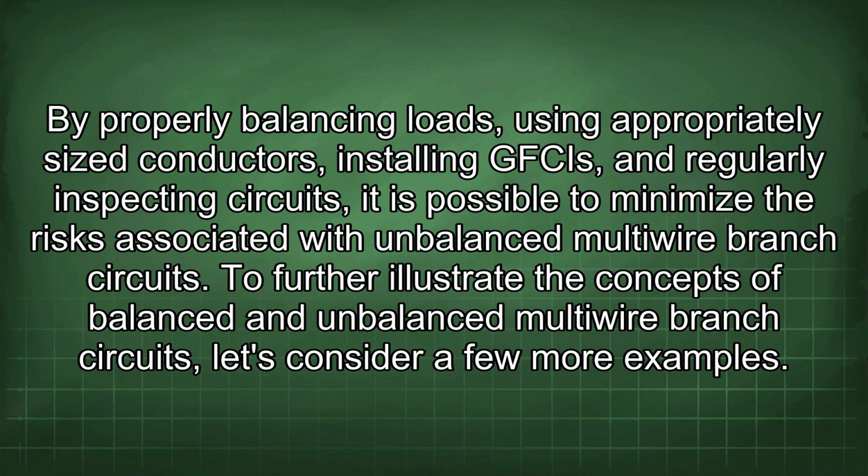By properly balancing loads, using appropriately sized conductors, installing GFCIs, and regularly inspecting circuits, it is possible to minimize the risks associated with unbalanced multi-wire branch circuits. To further illustrate the concepts of balanced and unbalanced multi-wire branch circuits, let's consider a few more examples.